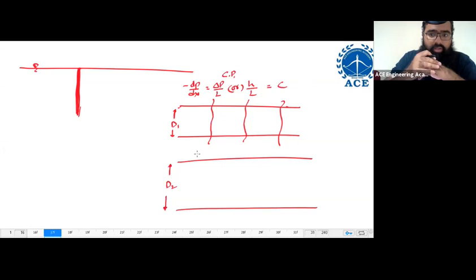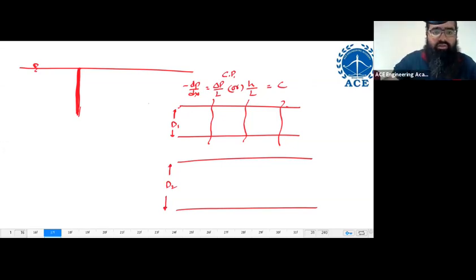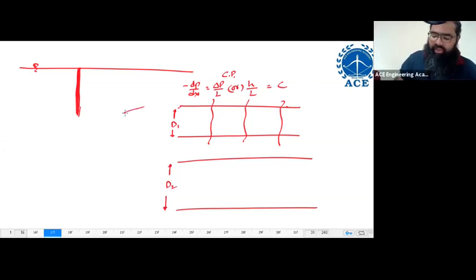Are you following? Yes, sir. So over here, who plays the more important role, diameter or length? Diameter. It is the defining parameter here. And for a rectangular cross section, again, the cross section is important. We are trying to convert a rectangular cross section into its effective circular cross section. Its effective circular cross section has a diameter, and that diameter is called the hydraulic diameter.